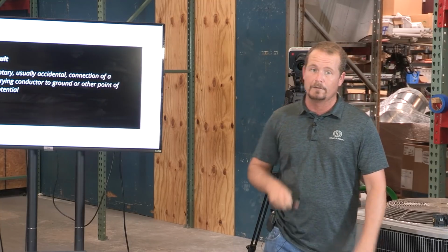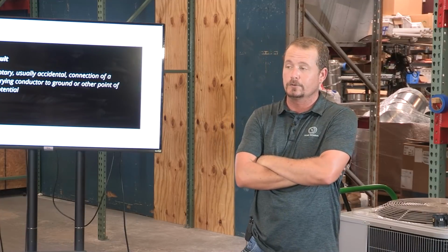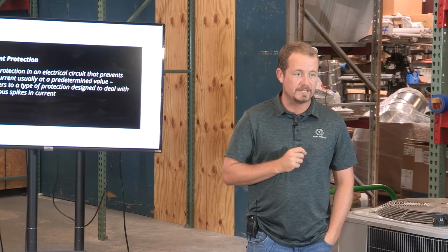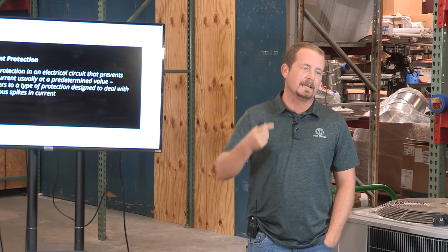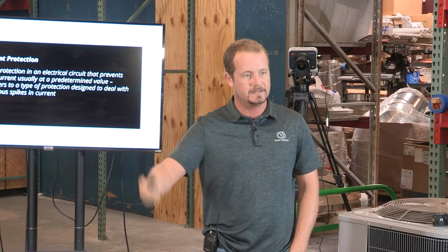Now, specifically with ground fault in the NEC, National Electrical Code, I believe the 2020 NEC specifies that we're going to have to start having GFCIs on condensers. And that's going to be a very interesting new form of nuisance call. In the same way that ground faults trip in garages when people hook up their old refrigerators to them, we're going to start running into that. Did you just say GFIs have to be on the system? They're going to be most likely in the disconnect or in the breaker that feeds the condenser.